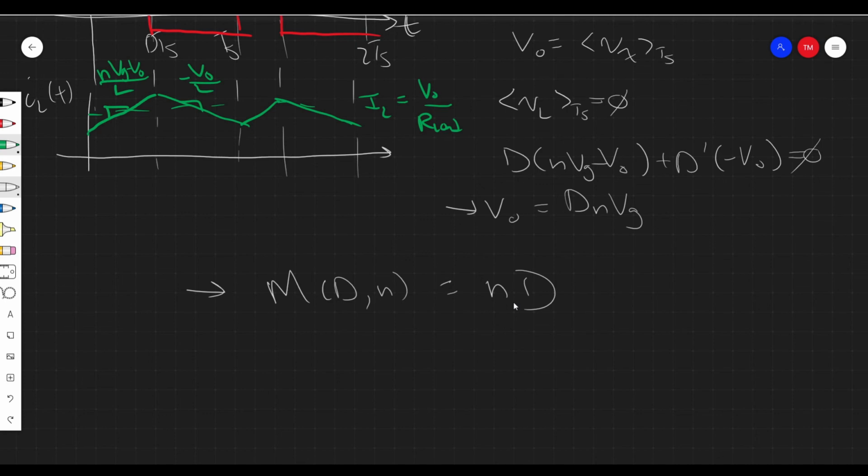So using this buck derived topology, we can actually step up the voltage by choosing a turns ratio that's larger than 1, right? So if, say, N is 100, then we can increase the input voltage by a factor of 100 and then step it down depending on our choice of D. Right? That is totally possible. So by using transformers, we can actually get buck converters to step up voltages, right? And sometimes that's useful. We can also get it to really step down voltages. So we could choose N to be really small, like 0.001, and we could turn a 100 volt input voltage down to less than 1 volt. That's totally possible.